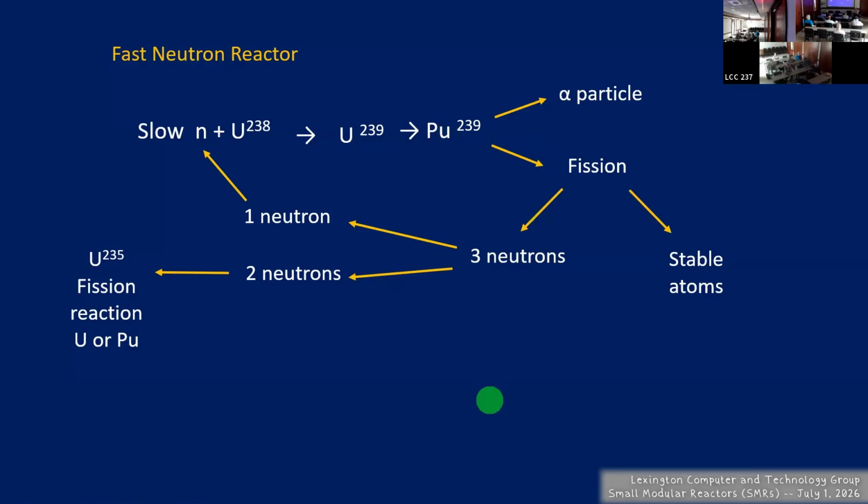This is like an eternal energy machine. And it will do that, except that with all the radiation, the cladding of the U-238 breaks down. The thermal cycling of the whole unit breaks down the outer edge. And there's one other thing that happens. You get the breakdown products of plutonium, the subnuclei. They start absorbing neutrons. They contaminate the system. So a fast neutron reactor won't last forever. It'll last for years, but it won't last forever.